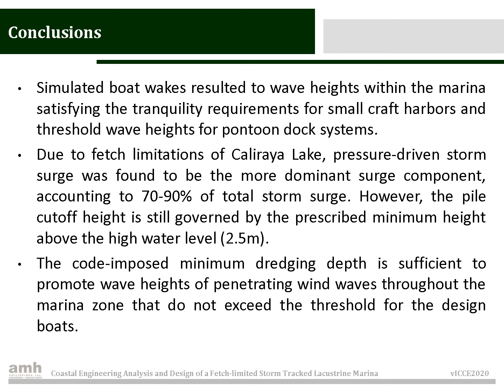Due to fetch limitations of Caliraya Lake, pressure-driven storm surge was found to be the more dominant surge component. However, the pile cutoff height is still governed by the prescribed minimum height above the high water level, not by total storm surge. And lastly, the code-imposed minimum dredging depth is sufficient to promote wave heights of penetrating wind waves throughout the marina zone that do not exceed the threshold for the design boats.